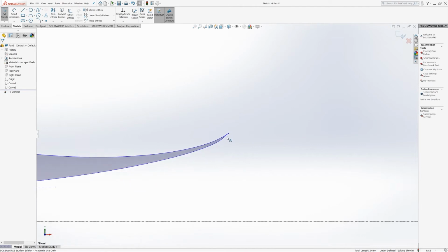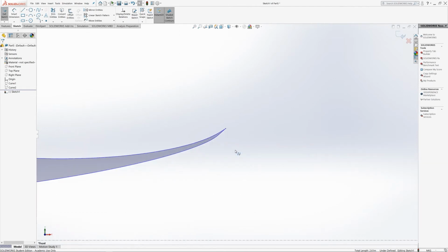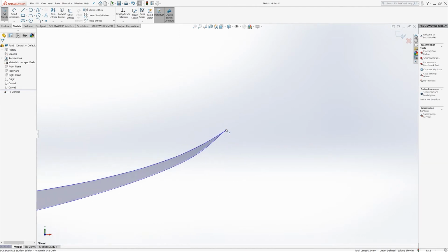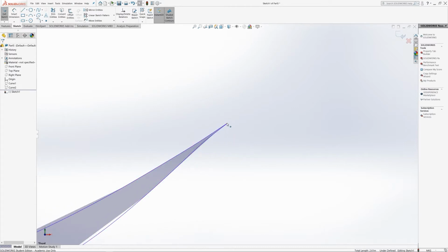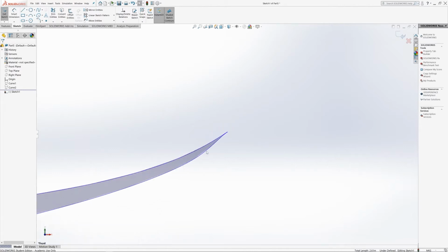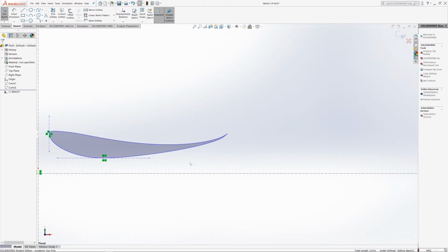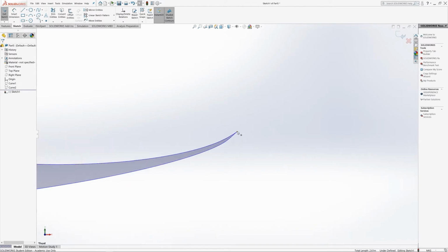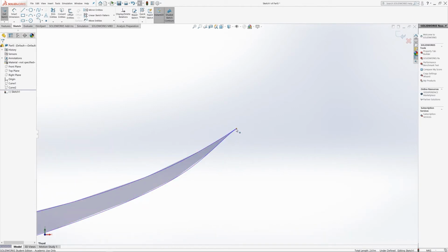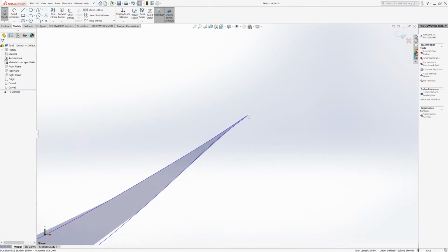Also, in reality, when we manufacture these wings, they're not going to have this sharp trailing edge. They're going to have some radius, because otherwise it'll be impossible to manufacture. So it is less than ideal in terms of the efficiency of the airfoil. This sharp edge is the most ideal case, so the wing will be less efficient. But that's a real life problem that the wing will suffer. So it will be useful for us to include it in the simulation to give us better accuracy.